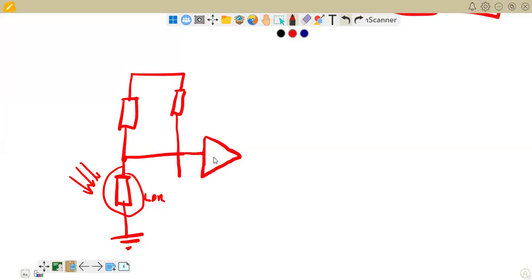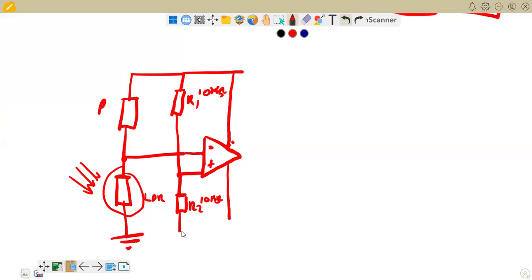And then the negative, the positive, and then it's connected directly to resistor R2. So this is marking resistor R1, that's P, and R2. These are 10 kilo ohm resistors. They are forming a voltage divider, 10 kilo ohm, and also 10 kilo ohm here, and from there this is positive and negative. And then this is grounded as much as this one is. Pardon me, it's a little bit poor. So is this one also grounded?